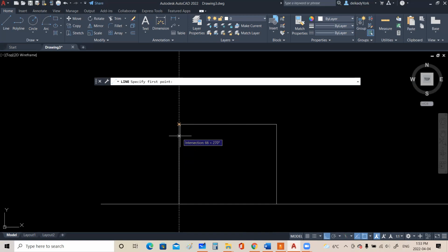value, a numerical value that is actually changing. So I can type in the value that I want, and again, make sure that you are hovering on that corner point and then going down. Hover and go down, and once you see that dashed line, this means that I can actually pick any point that I want to start drawing the line from. And I want to make sure that this point in height is at 50. So I'm just going to type 50, enter. And now you can see that we are drawing the line from that 50 after I took 50 millimeters from the corner point that we drew.